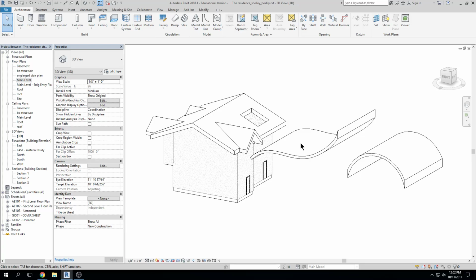Who asked me about the ceilings? Anyway, about putting gypsum board on the bottom, maybe it was Junior. If I create a floor, I want to create a ceiling up underneath that floor, even though I could technically define gypsum board on the bottom of my floor. The reason I don't do that is because then lights don't recognize a floor as a hostable element. They have to have a ceiling.